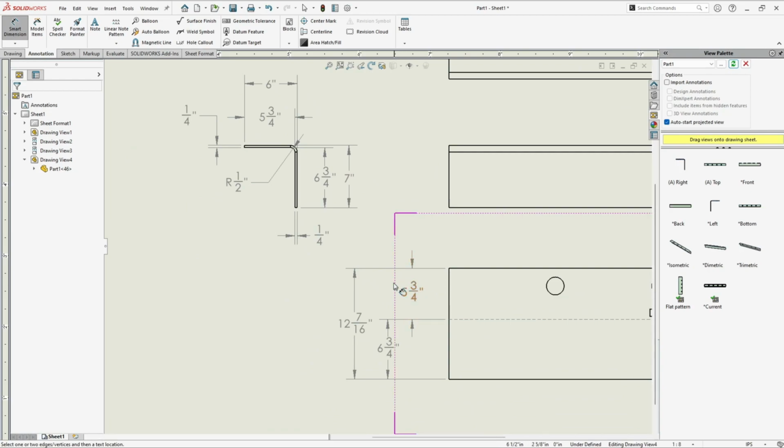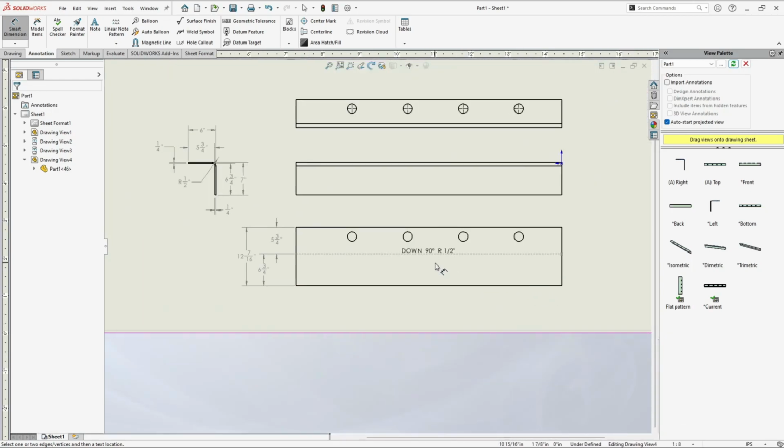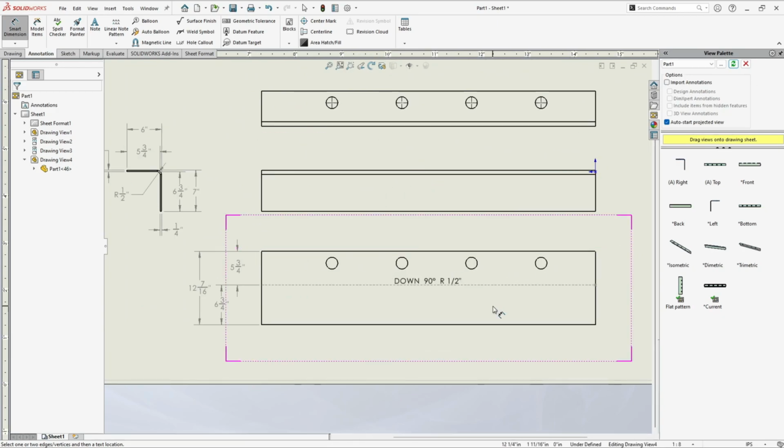So in this you can see 5 3/4 inches for this flat pattern, and in the job we have the same 5 3/4 inches which is matching. So it means the flat pattern is perfect. Now let's check for the rest of the part. 6 3/4 inches from the bending line till the edge, 6 3/4 from the bending line till the edge. So this flat pattern is absolutely matching the requirements given by the customer. So this will be our flat pattern for the given job.